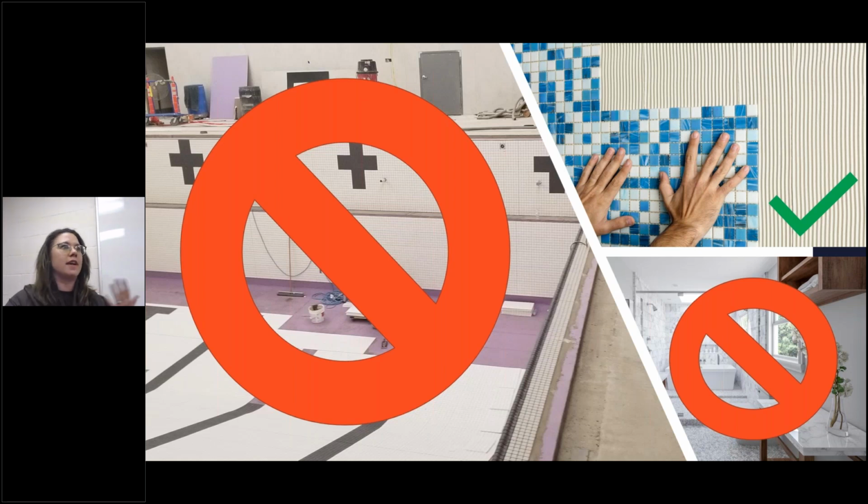And given the fact that I think the average tile size nowadays is far bigger than it was when mastics were maybe a little bit more popular, maybe 10, 15 years ago, you have to realize that part of the reason a lot of people have gotten away from mastics is they just don't work as well with those big tiles. But again, they still have their place. Backsplashes, smaller tile, areas that don't have a lot of water exposure, they're really, really easy to use. Just open it up and you're ready to go.